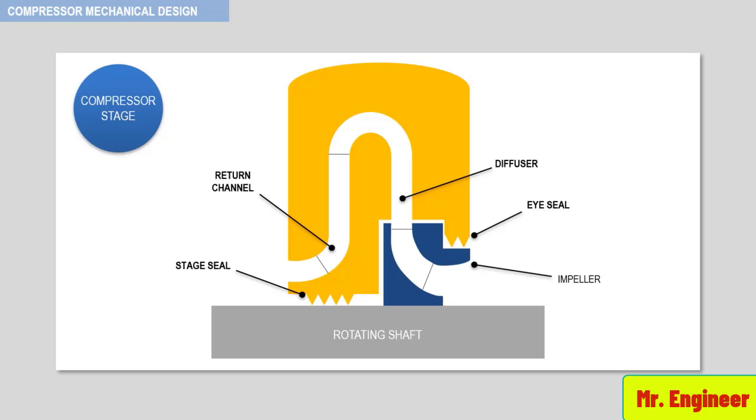Diffusers are usually vaneless, but can be vaned or scrolled to increase head produced per stage. Older designs with vaned or scrolled diffusers often encountered problems with impeller sidewall breakage, caused by fatigue of the impeller side plates resulting from alternating pressures at the impeller discharge. This phenomenon was caused by the pressure buildup from blade passing interference between the impeller and diffuser vanes. The classic fix is to scroll the impeller wheel between each vane.